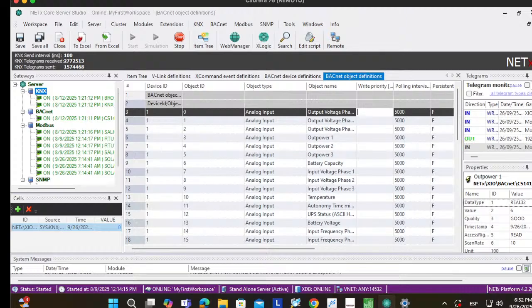So my advice: if you have a device that you need to get information from very often, very fast, all the time, every millisecond, second, or whatever, don't go KNX. KNX is not the best solution to get information from the bus every millisecond. Go for solutions like Modbus, or BACnet, especially Modbus.